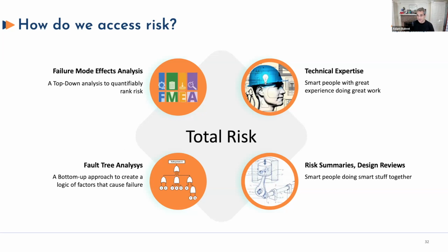FMEAs done incorrectly is what you want your competitors to do. It beats morale and drags on and drains resource, and it's crippling. FMEA done correctly is pretty much one of your best tools to guide what you do in a program. You have fault tree analysis to help you when you get down to specific issues and you want to break down the elements that can drive it.